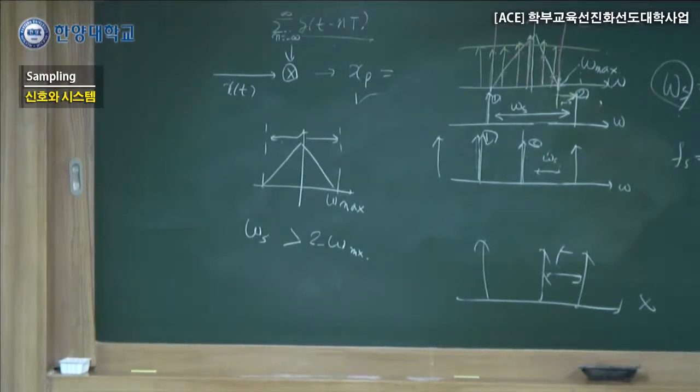So to solve it, we have to make the sampling period shorter, meaning that we have to increase our sampling frequency. This also corresponds to this criterion. It tells you that the sampling frequency cannot be smaller than a certain value, at least larger than 2 times the largest frequency of the signal. But that's a minimum rule. To get better data, you have to have 5 times or 10 times larger than the original value.